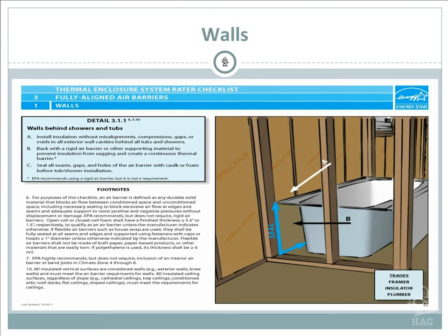Okay, so walls, this is the picture out of that little pamphlet we sent you. Right in this area is the area being missed by most of the insulators, and it's right behind that bathtub. So what should have happened is your seal plate should have been caulked on the exterior. This should have been insulated, air barrier, and your tub could go in at that time.